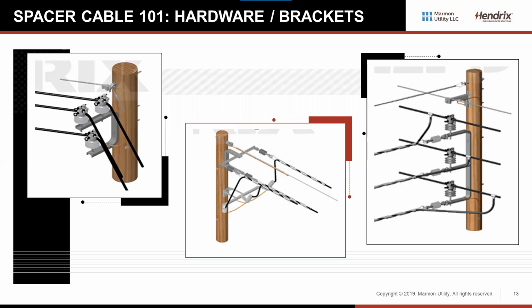So we've got specially designed grips that are actually coated so that the electrical interaction between the grips themselves and the surface of the cable is more compatible. So that you can keep that covering on and you don't get any excess leakage current that'll cause a breakdown in the covering. Because the phases aren't under any great deal of tension, we can even roll those to vertical, and that's what we show in the right-hand picture. We've got the standard tangent, but we've rolled it to vertical, and then there's a three-phase tap that comes off vertical as well.